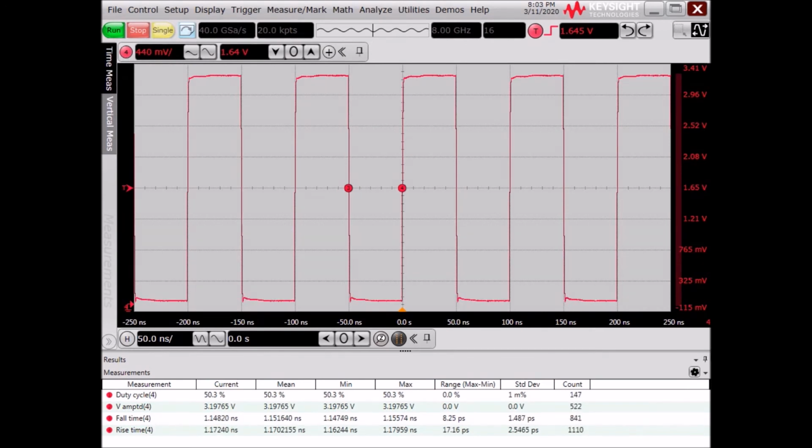Rise-fall time of SiTime LVCMOS devices is specified for either 20% to 80% thresholds or 10% to 90% thresholds. In our example, we are using our Elite Platform TCXO device for which rise-fall time is specified for 10% to 90% threshold, so we will set it in the measurement threshold settings.